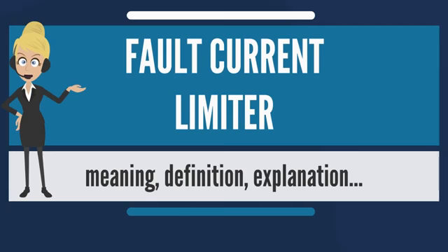A fault current limiter is a nonlinear element which has a low impedance at normal current levels, but presents a higher impedance at fault current levels. Further, this change is extremely rapid, before a circuit breaker can trip a few milliseconds later. High-power circuit breakers are synchronized to the alternating current zero crossing to minimize arcing. While the power is unstable during the fault, it is not completely disconnected. After the faulting branch is disconnected, the fault current limiter automatically returns to normal operation.